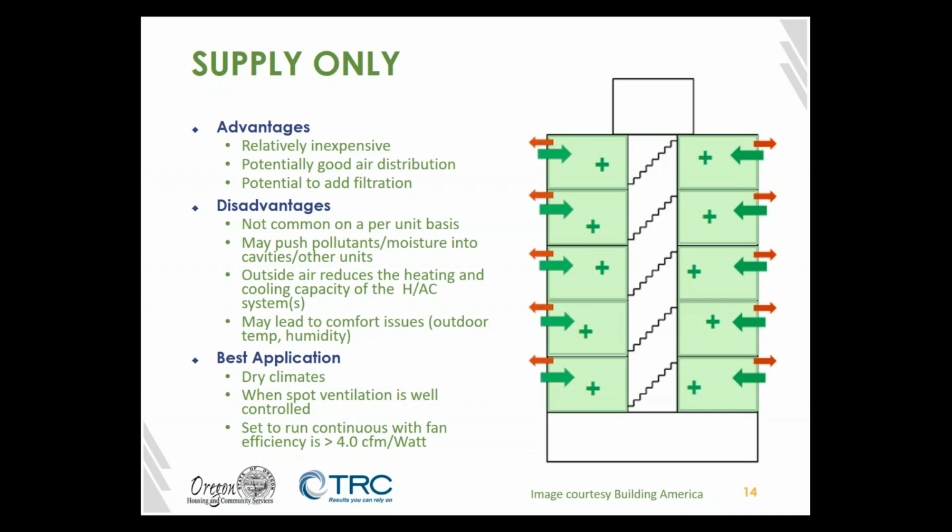You can do a little bit more intentionality of the distribution, right? Your air is coming in exactly where you put that fan, or the end of the duct line from that fan. And so you can target it and get that distribution. Now, you're still not quite sure where this air is going. Is it really going outside?